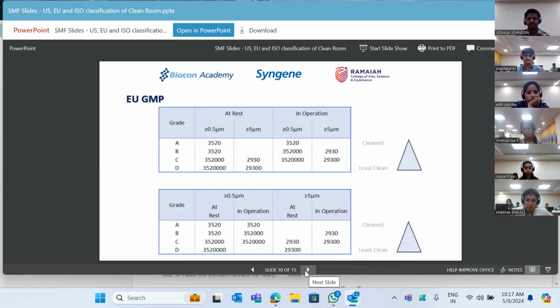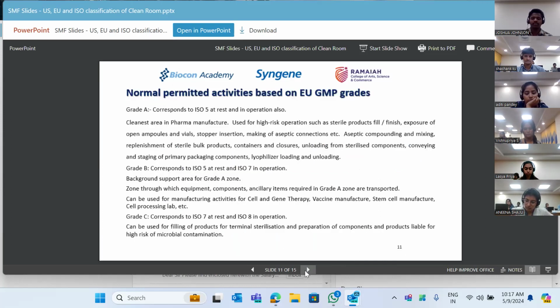Okay. Now there is one more point which I wanted to tell you. ISO 14644 only deals with particle contamination. But while you are going into the field and practically looking at it, ISO 14698 biocontamination control is also a new area which we have to focus on, in terms of the rules and the methods governing the biocontamination controls. ISO 14698.